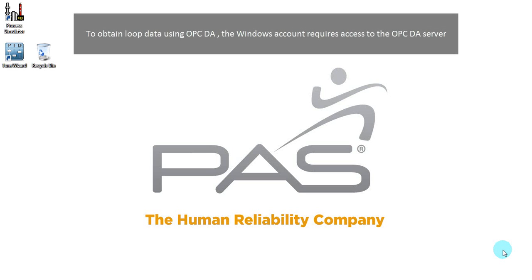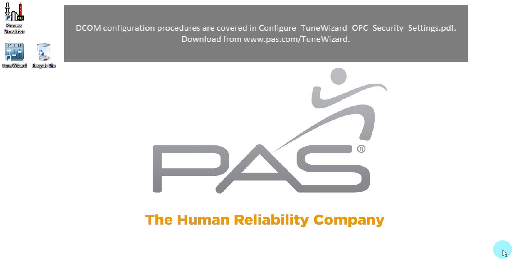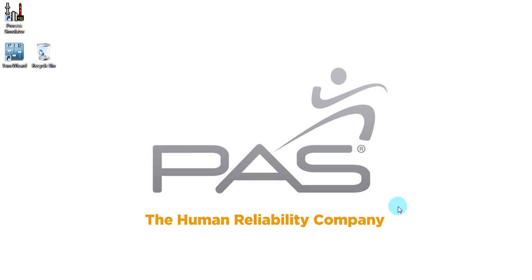To start the configuration for TuneWizard, there are a couple of prerequisites. The first one is the DCOM configuration between the client and the OPC server. There is a link on your screen right now to where you can access the procedure for DCOM configuration. The second item is to make sure you start OPC enum services.